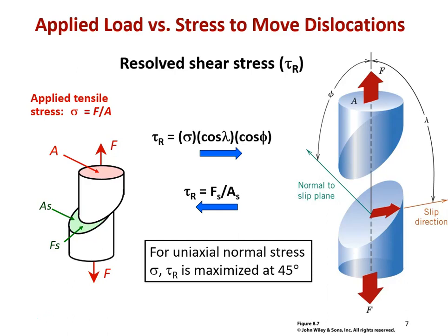the applied stress. So we call that resolved shear stress because what we've done is we've resolved the vector loads or the vector stresses that we applied to the material. Remember, we control what we apply, but the geometry of the material determines what is actually seen at any point in the material. So that's applied loads versus resolved loads, or loads in a given direction in the material stress